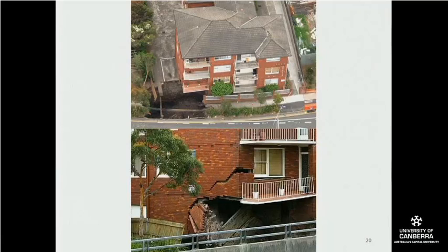So once you get a lot of water in there, if you have no control over it, it just erodes away the earth, creates a big hole, and the corner of your apartment starts to fall away. But I thought this was quite amazing that certainly in this case it's the concrete slab that's holding up this corner, but what's holding this up is actually just the loading on the brick being transferred down to a different part of the footings.